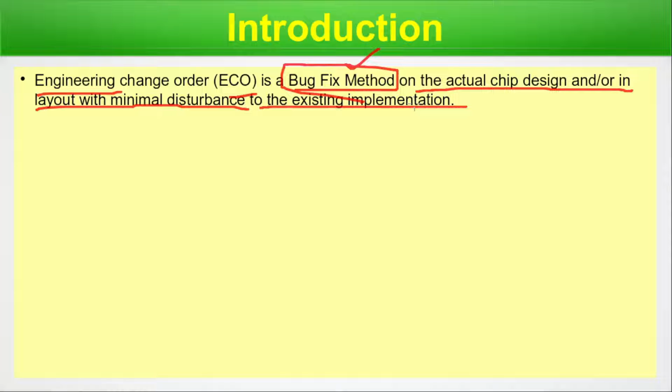I have already talked about different types of violations in this FAQ series, like IR drop violation and others, and also there are various rules that have to be passed for the physical verification. And when these steps are iterated multiple times, we implement delta changes, and because of those delta changes, somewhere something may goof up which may actually get popped up on the silicon, not before that. How can they show up in the silicon? We have to do the ECO process. So we will talk about various methodologies today, how things can be preventively taken care of.